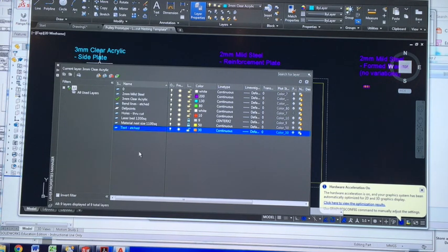So when the technician opens up your file in the toolpath software, what they're preparing is to tell the machine which layer and how far it's cutting. So it'll take everything that's on the 20mm cut layer and tell it, okay, this is the layer you're cutting down to 20mm. All right, that's the basic process that goes through.